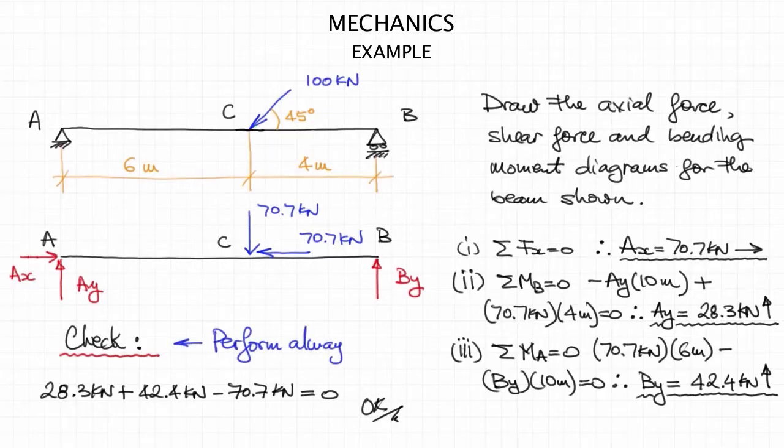So my reaction forces are correct, which means I'm okay to proceed. So always perform this check. Make sure that your reaction forces are always correct, because as I mentioned, everything that you will do will be wrong. Very, very important to perform that check.